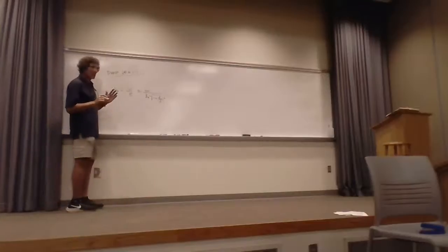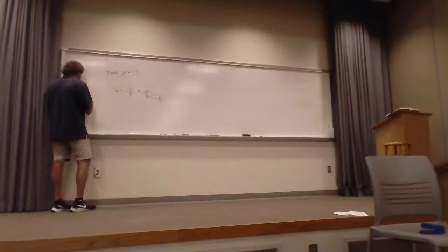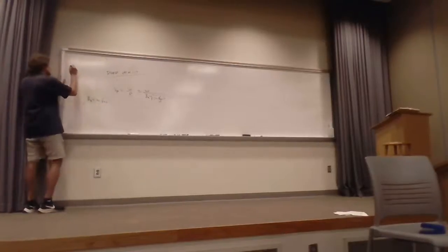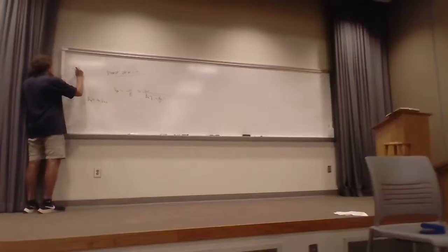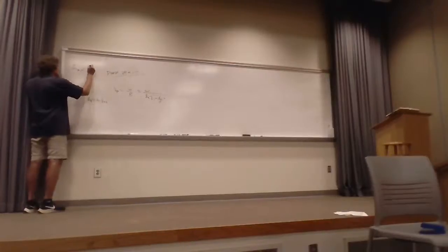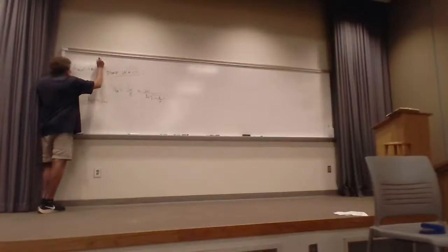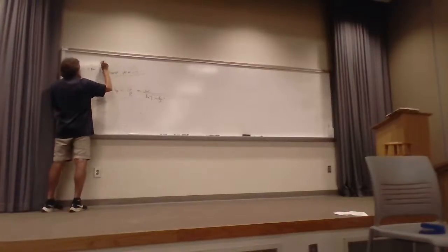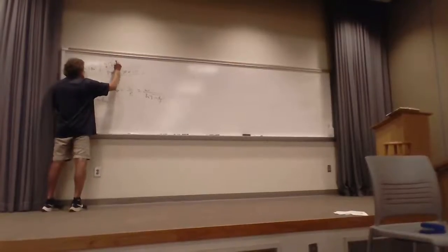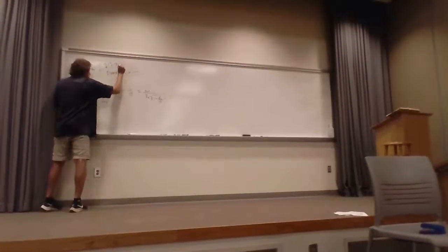Now, beta unguided is just omega times the square root of mu epsilon. And fc, which has to do with the mode number, is equal to c over 2 times the square root of epsilon relative, times the square root of (m over a) squared plus (n over b) squared.